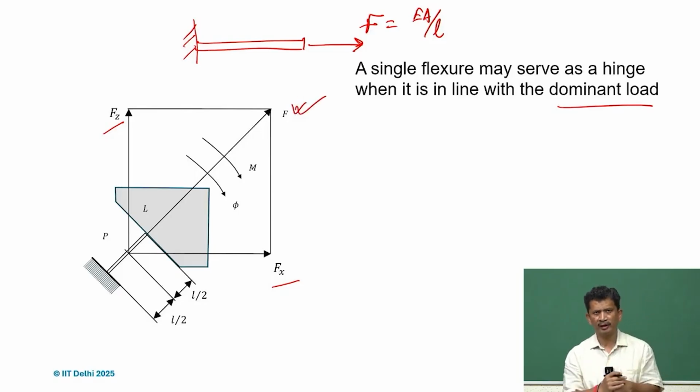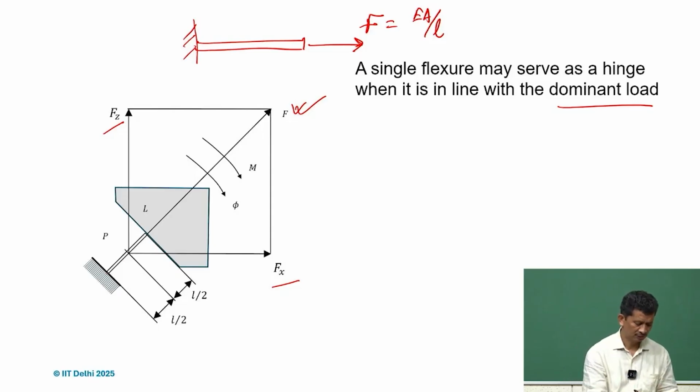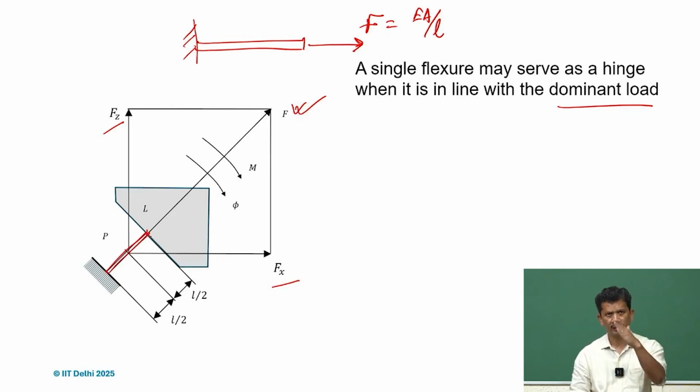So we don't have to align to x or y, but we orient that flexing part AB along the force direction. So what happens because of that force? Yes, it's an axial load coming on the flexure element, and it's relatively rigid compared to bending and torsion.